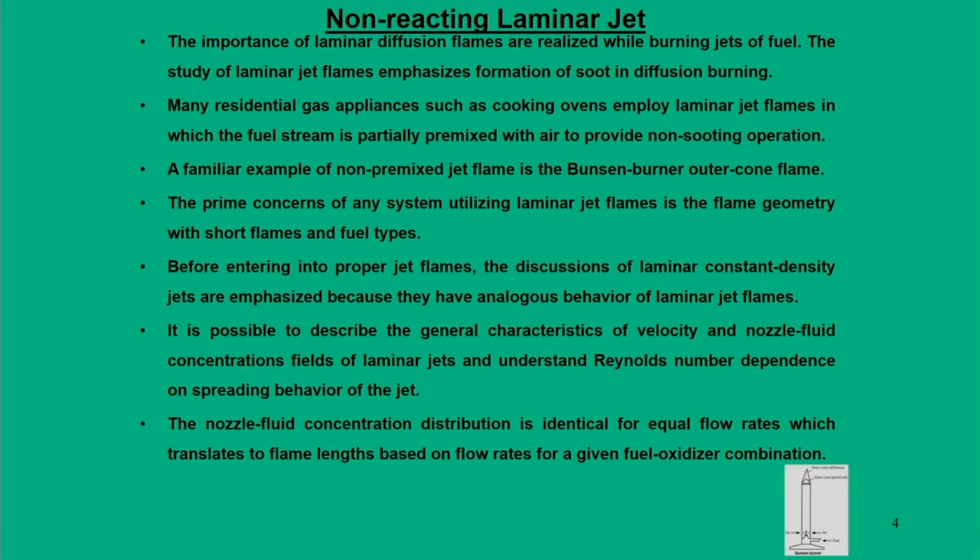So, all sorts of phenomena come into the picture. In an actual scenario, when the fuel is injected from a nozzle, it tries to diffuse within the air, and side by side the combustion happens. Combustion means that the density of the mixture keeps changing within the flame domain. As a result, the equivalence ratio also changes. But what we are trying to analyze here, we will see in a very hypothetical way. We view it as if a fuel jet is being injected from a nozzle and it tries to diffuse in the air, and during this diffusion process we assume that they are not reacting.